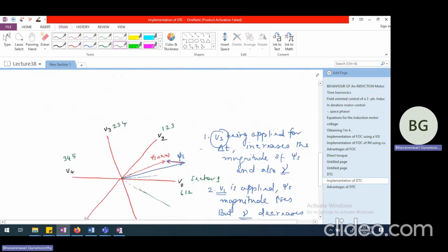So what we talked about was, this is V1, this is V2, all of them are of VD length. Rather than that, can I have one more voltage vector which is probably lying somewhere here? One more voltage vector which is probably lying somewhere here. So these can be obtained in multi-level inverter configuration. So direct torque control, when it is implemented with multi-level inverter, may be able to give much more accurate control as compared to what you see normally in our 2-level inverter case.